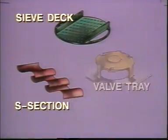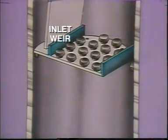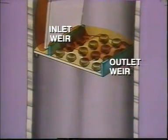Other types of trays include the sieve deck, S-section, and valve tray. They use different types of hardware to force vapors to bubble through the liquid on each tray. On each tray, there is an inlet and an outlet weir. These weirs act like dams to distribute liquid across the tray and maintain the proper liquid level.